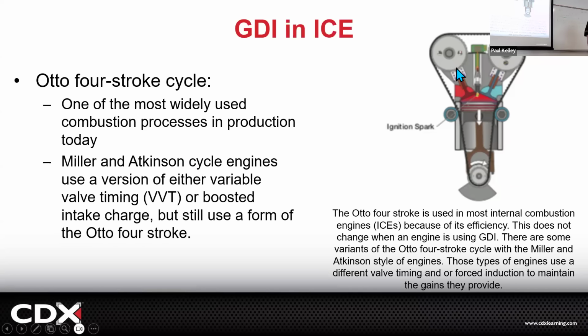We couldn't really hang the intake valve open longer before because we'd push half the fuel back out. So instead of injecting it on the intake stroke, we're like, no, hold off, do the intake stroke, leave the intake valve open, push half the air back out, then close the valve. Let's say it's a 3-liter. Now let's make it a 2-liter.